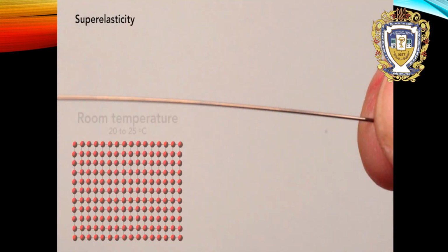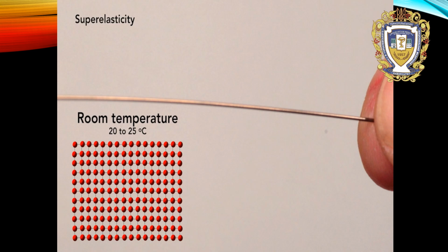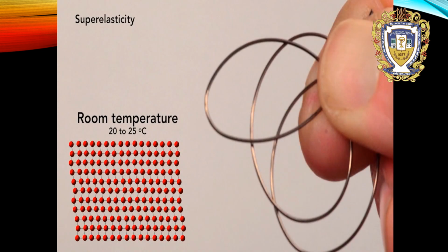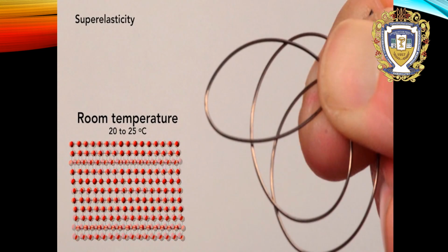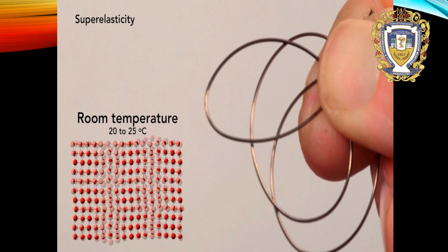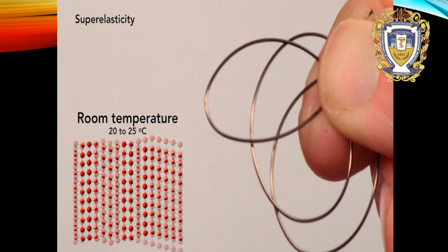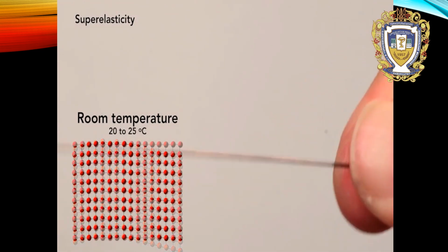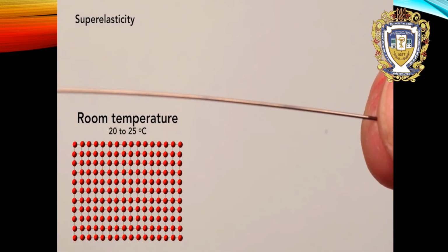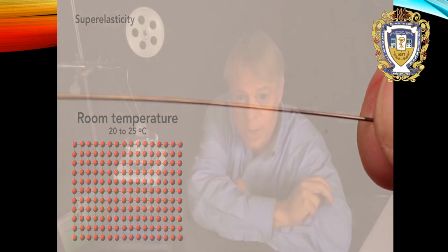Now, let's look at a nitinol wire that showed superelasticity. It's been conditioned so that its crystal structure is these tidy, neat squares at room temperature. It would form the twin structure at minus 15 degrees Celsius, so a much lower temperature than the shape memory effect. When I apply an external force to the wire, the crystallites and the grains deform into the rhombuses, whatever mix of those would allow it to accommodate the reshaping. When I remove the force, then, because it's at room temperature, it returns to the tidy squares.